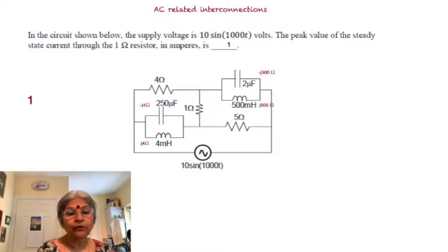Infinite impedance is always reflective of an open circuit. So also for the top parallel circuit, where we again utilize omega. First for the inductor, to get its impedance as equal to 500 milli into 1000, which is equal to 500 ohms. And for the capacitor, you notice the 2, which makes it very clear to us that it's going to come on the denominator. So we are going to have again 5. What is it? It is 10 raised to 6 divided by 2 into 1000. In other words, that's also minus j500 ohms. Again, in parallel together this gives rise to an open circuit.